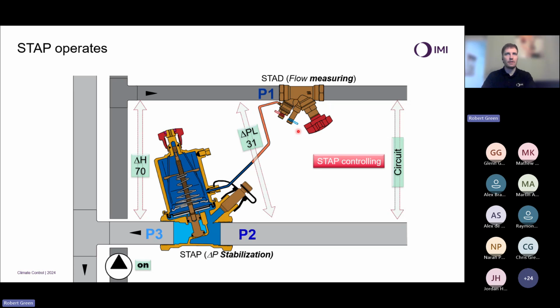So now if we get an increase in pump head once more, because something else has happened in the system, my DPCV is going to react to that, and it's going to provide a stable differential pressure. And you'll note that it's not entirely stable. It is increasing slightly. That's because of what we call the proportional working range of the spring and DPCV. A DPCV is by its nature a proportional controller. And for any of you who have done anything with control, you will know that proportional control means it has to see an error. So we must see an error to act upon it. If there's no error, the valve can't act.